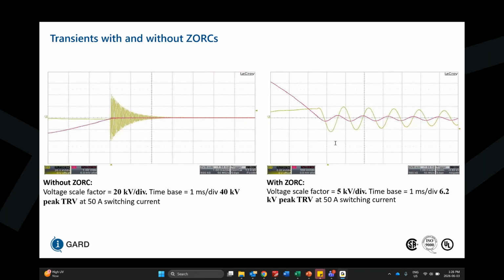Does this work with VFDs or are there technical issues? I've seen some VFDs have surge suppressors on them, but I am not sure if it can mitigate in relation to harmonics per se, but definitely just the switching transients it'll be able to handle.